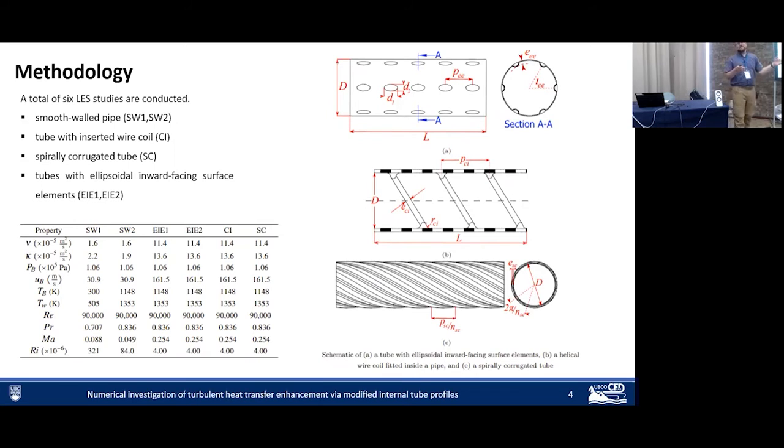And so for the purposes of simplicity and also numerical stability, we are making the assumption that the fluid properties can be assumed to be constant. And that's not correct, really, in real life, but there's not a significant range of temperatures as the fluid moves through the domain. And so for our purposes, we treat the fluid as a composite fluid with average properties, the average of the temperatures between the wall and the entrance of the fluid.